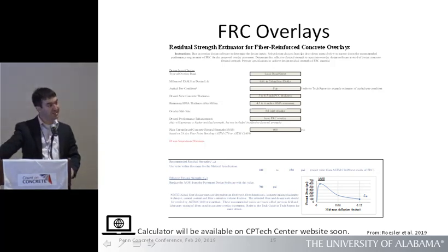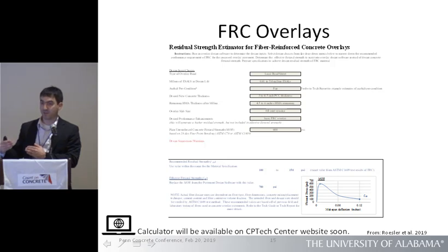Now notice, this is not telling you what fiber dosage to use. It's just telling you whatever fiber dosage or fiber type you're using, it should hit at least 100 psi residual capacity according to ASTM C1609, or greater, you can be better, to meet this design criteria.